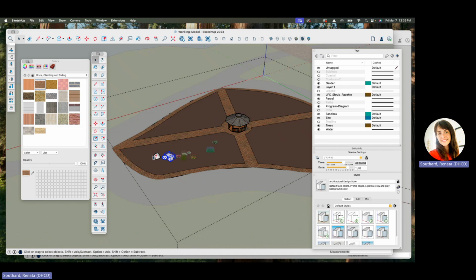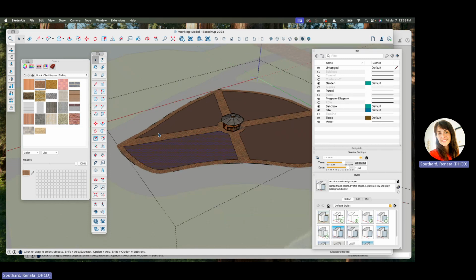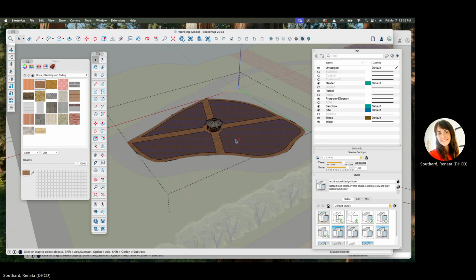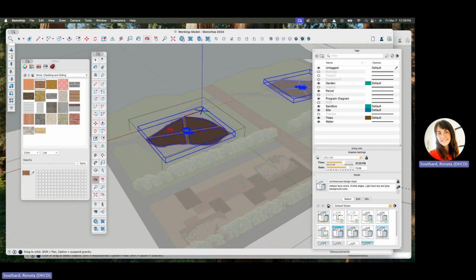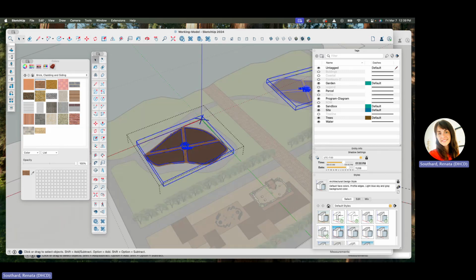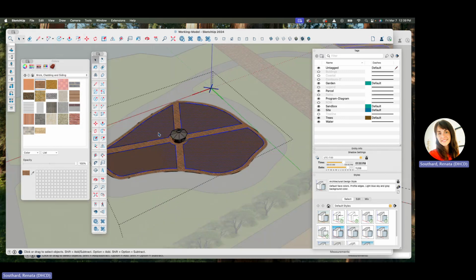I'm actually gonna get out of this group for a second. I'm gonna select these and copy them, Command C. Now I'm out of that group, but I'm still inside the component. I'm gonna hit Edit, Paste in Place. Then I don't want the actual geometry, so I'm gonna delete the center of them, which will leave me with a line.